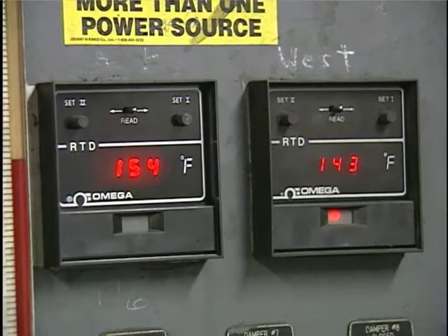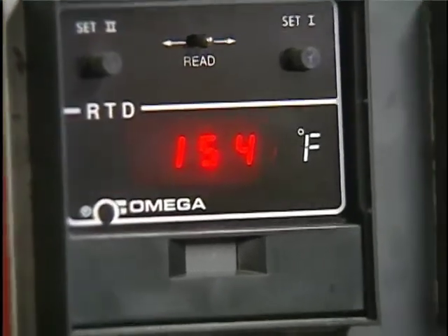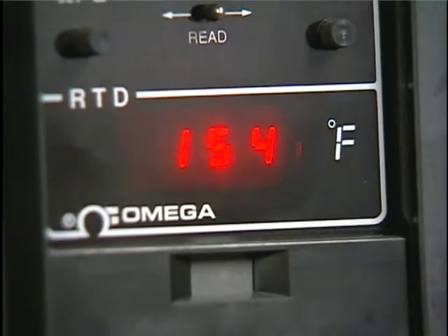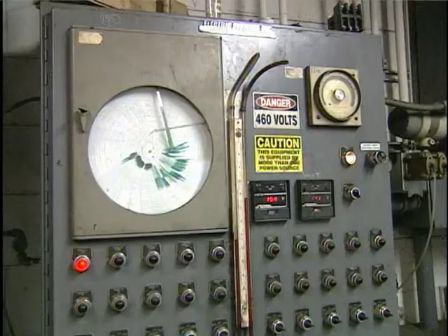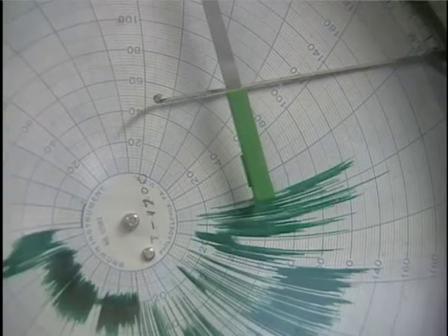The inlet and outlet temperature of the collector should be checked. The inlet temperature should be compared to the temperature limit for the fabric being used. Frequent exposure to high temperatures can damage the fabric and cause holes to develop. Low inlet temperatures could result in acid, moisture, or organic vapor condensation. Acid condensation will weaken the fabric material, causing holes to form.